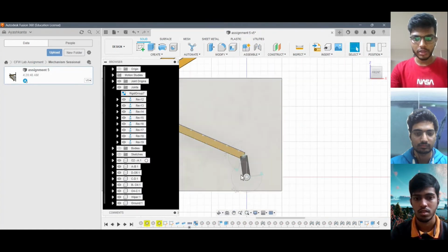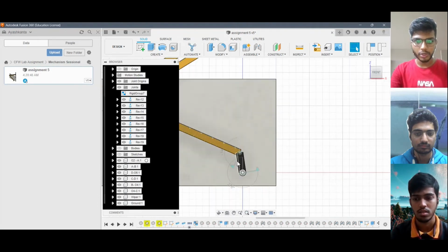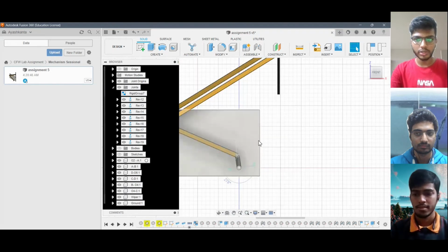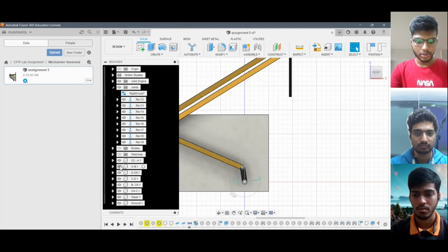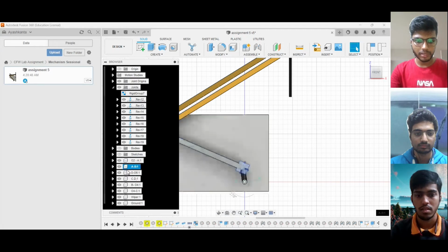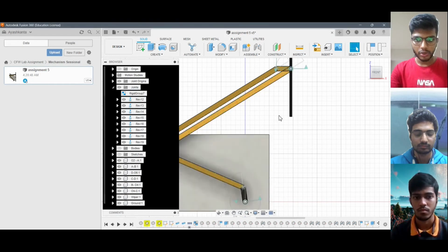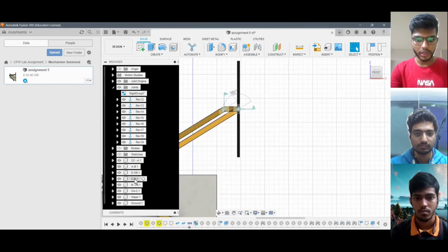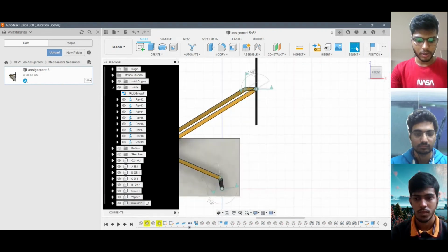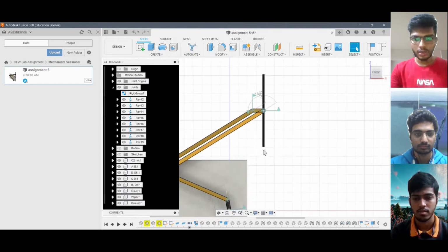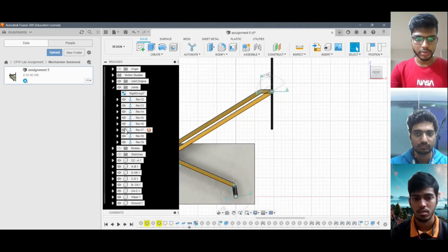When our motor rotates, this is the crank. This will be rotating, and this is the only thing that controls our mechanism. So this is the O2A link. After that comes the AB link, which connects to the rigid body of O4C and BO4. At point C, we are attaching the wiper. This is the basics of how we created this model.